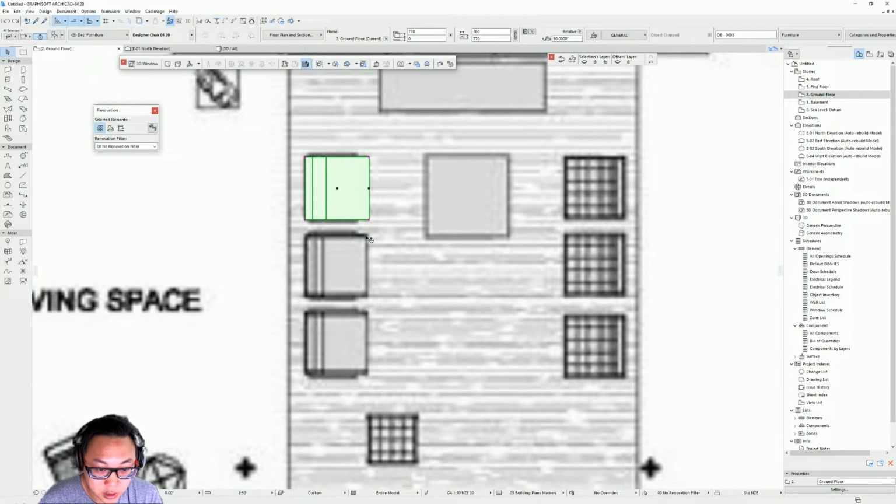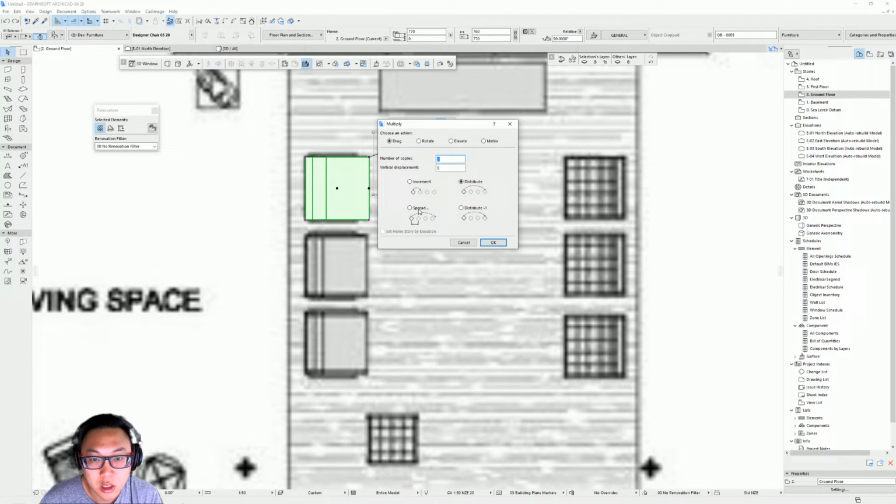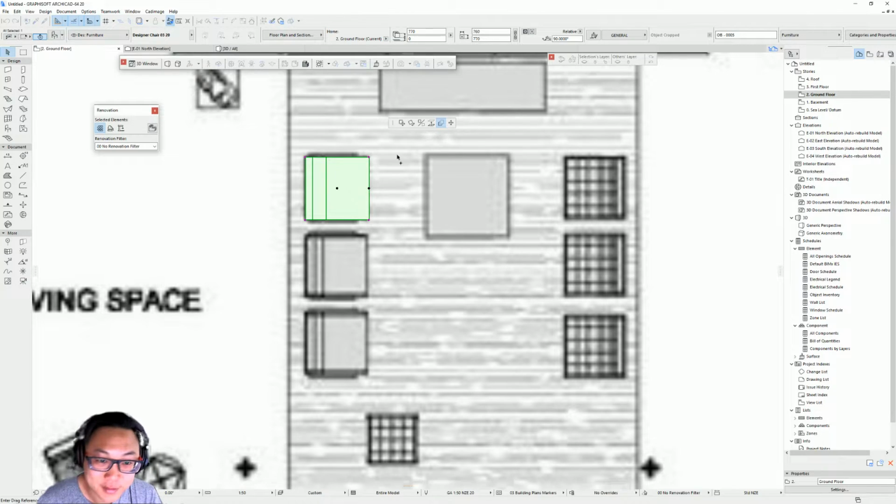And I know the distance that I want that to be. It's gonna be 180. So I can take this chair and I can spread. So it's 770 plus 180. So it's gonna be what? 800, 960. So now I can take from that point, it's gonna make a space of 960 and create another copy. And every 960, it's gonna create a copy. If you press shift, it's gonna be aligned to the axis.